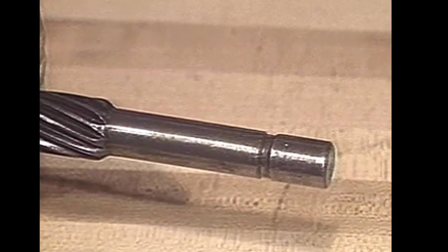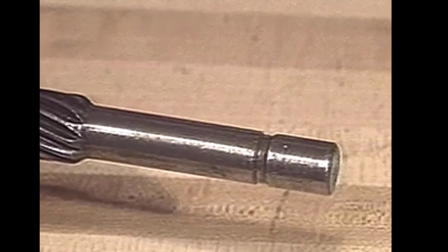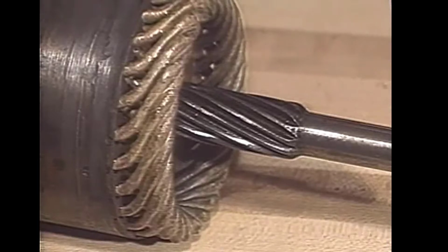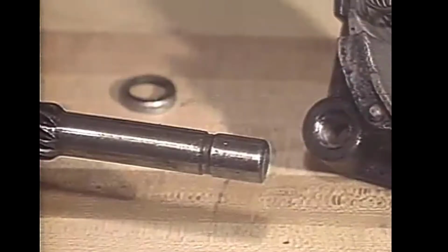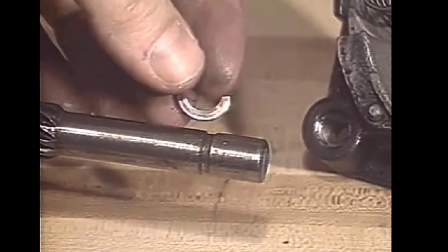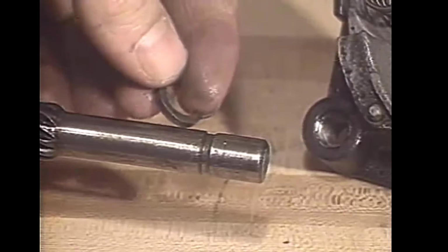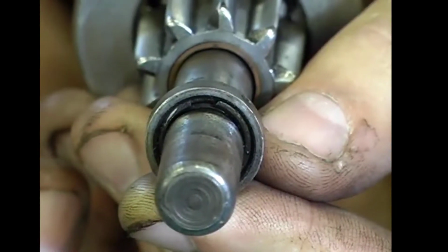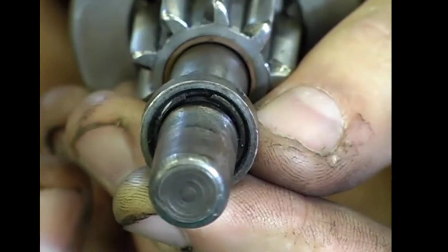On the other end of the armature shaft, note that a groove is machined for a snap ring. Spiral splines on the shaft are used to make the pinion gear and clutch turn with the shaft, but they allow the gear to slide back and forth. Some starters have a thick C-clip type snap ring like this one to secure the pinion gear assembly. A cup-type washer fits over the C-clip to protect it.